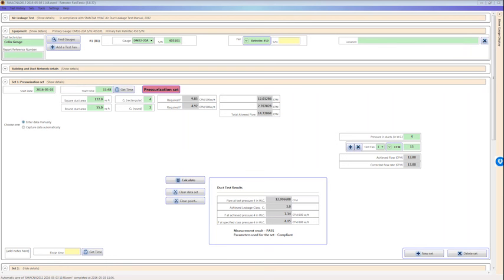So we'll be sending everyone that list. Jeff had the question: if we don't hit the test pressure and we use the add feature, what's the accuracy, especially if you have results that are incredibly low, like your example was? What if I only reach 0.2 inches of water column and I'm trying to reach 6? I was going to come up with a little table that would show you the expected accuracy at the extrapolation pressures, using conventional equipment and using ours.